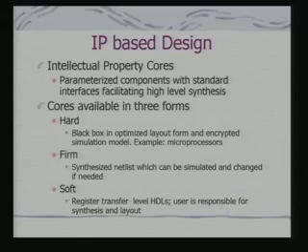Now, these cores are available in a variety of forms for this purpose. We call them hard core, firm core or soft core. In a hard core, the designer of a processor provides the design itself in a black box form, in an optimized layout.